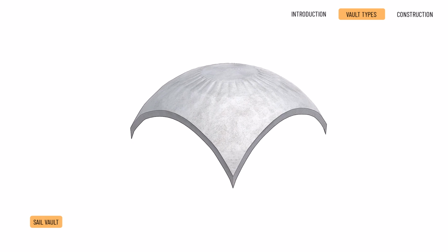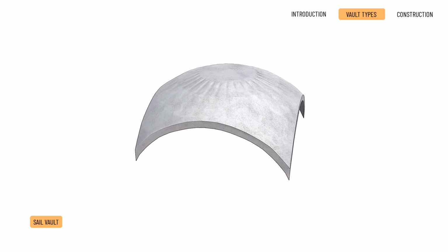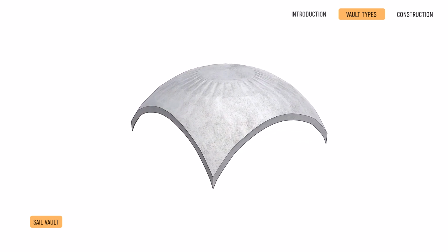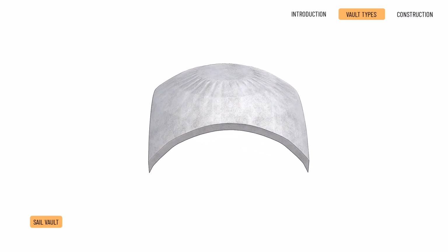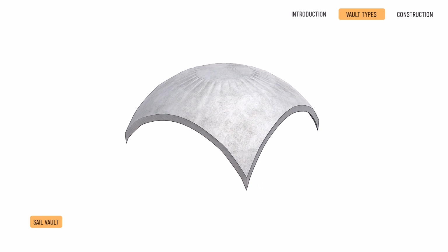Sail dome. The sail dome is also considered an open dome on all sides. It differs from the pendentive vault in that the vertical intersecting planes fall significantly inwards from the circle above which the dome is raised. The result is a segmental rather than semicircular frontal arch.